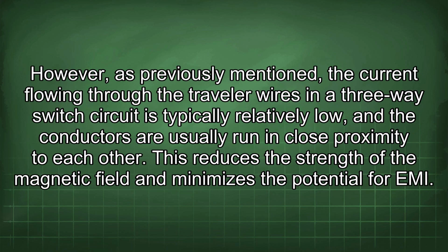However, as previously mentioned, the current flowing through the traveler wires in a three-way switch circuit is typically relatively low, and the conductors are usually run in close proximity to each other. This reduces the strength of the magnetic field and minimizes the potential for EMI.